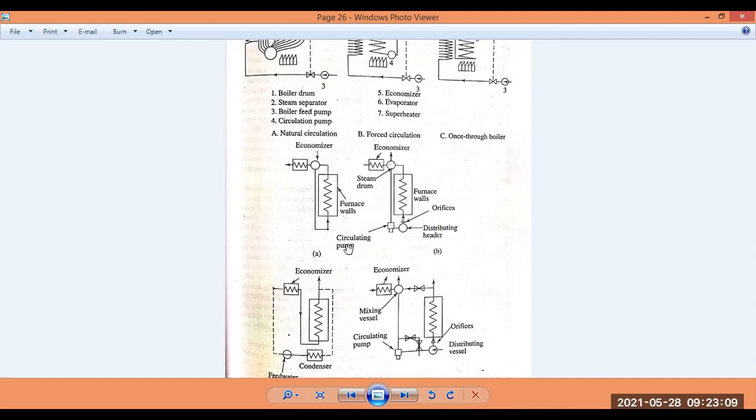Now water is supposed to be kept at 170 to 206 degrees centigrade, depending on the boiler pressure. The higher the pressure, the higher the temperature required for boiling. The high-pressure feed water goes into the economizer and leaves saturated or as a two-phase mixture of low quality. So what is going on?